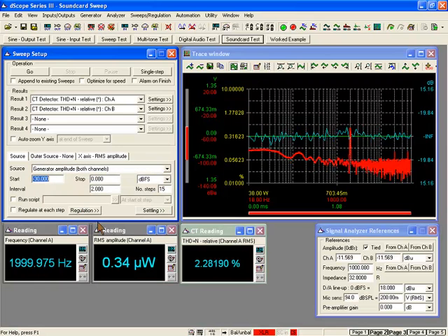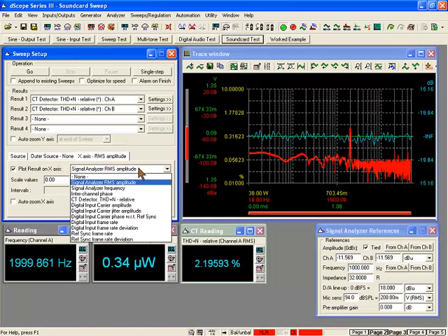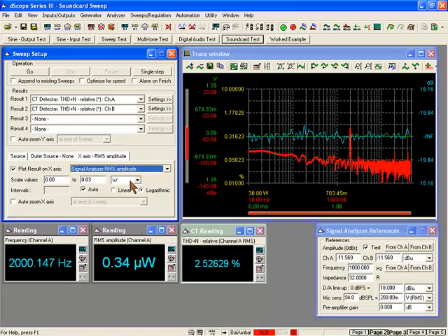And I'm going to vary my generator amplitude from minus 30 dB relative to full scale up to 0 dB, so maximum digital domain signal amplitude. And rather than plotting this against the generator amplitude, what I'd like to do is to plot it against the measured output power. So I've actually got my laptop headphone output connected to a 32 ohm resistive load, and I'm measuring the voltage across that load to measure the output power.